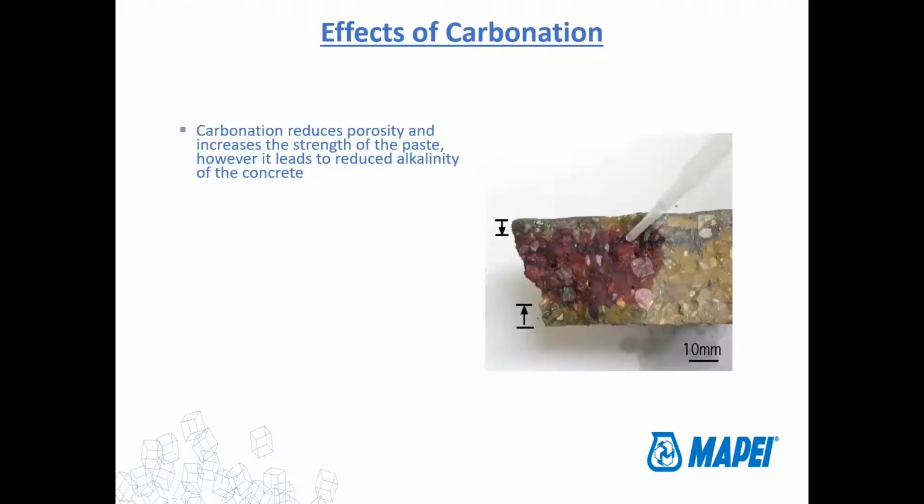So the effects of carbonation, basically, what happens is it reduces the porosity of the concrete. So you start to get those calcium carbonates forming within the concrete. So that's actually a good thing. What that means is with the formation of the calcium carbonate, we're getting a more dense concrete. Well, a more dense concrete, as some of you might be aware, is actually going to have a higher compressive strength because it's got more ability for load transfer between the aggregates and the carbonates that have been formed. So you actually would see a slight increase in your f'c, your concrete compressive strength, due to carbonation. So that's all well and good.